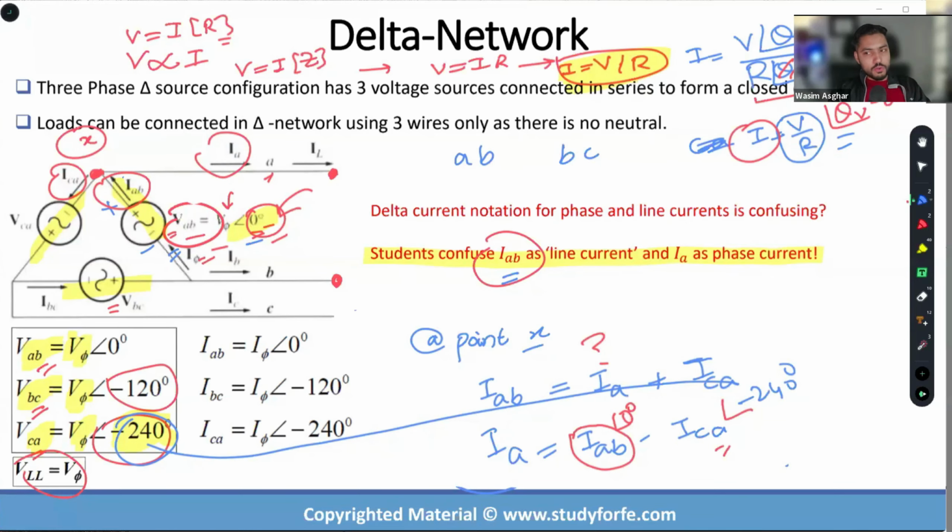So let's see where this goes. Assuming that we have a balanced system, as I mentioned, is the one where the magnitude of the current on phase A, phase B, phase C, the line currents, the phase currents are all equal. And the only difference is that they're 120 degrees apart, right? So if that is the case and we're dealing with the balanced system with balanced loads, as far as the magnitudes are concerned, we can just call them phase values for the current. And what we are left with are just the phase angles over here.